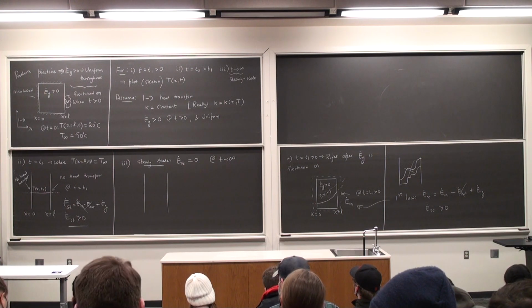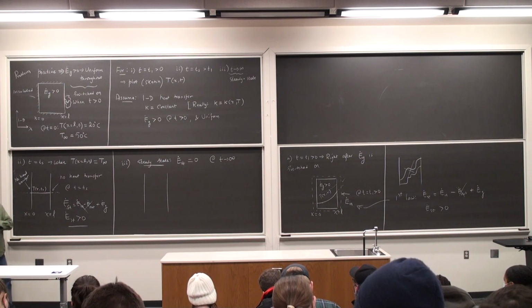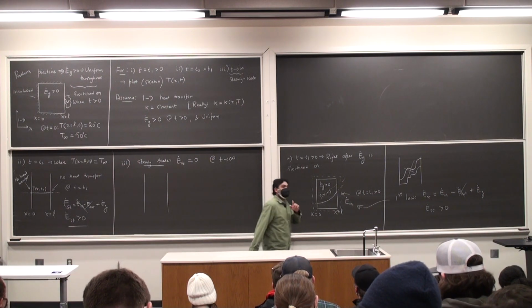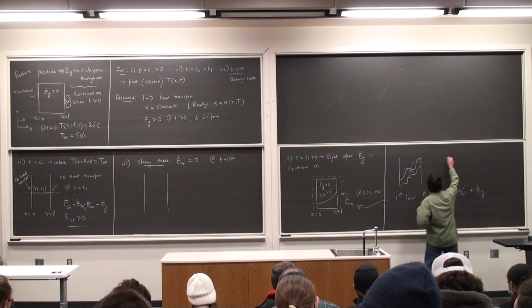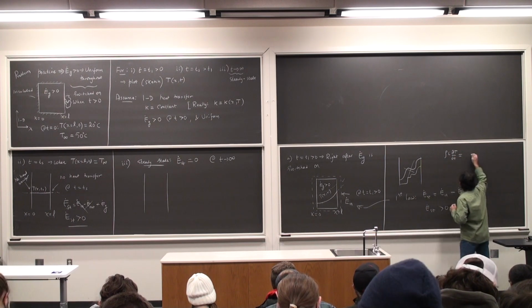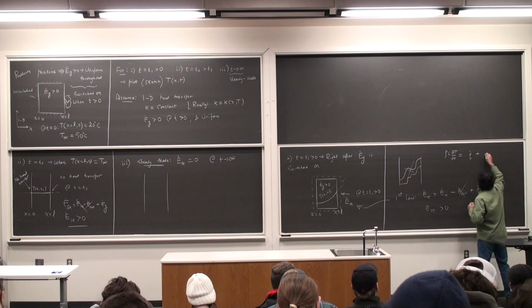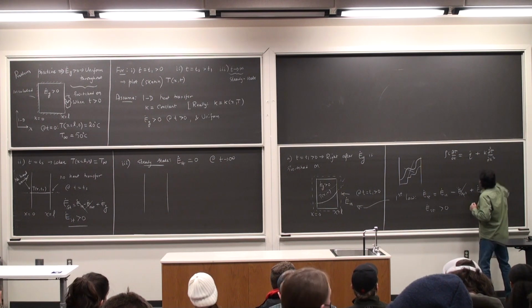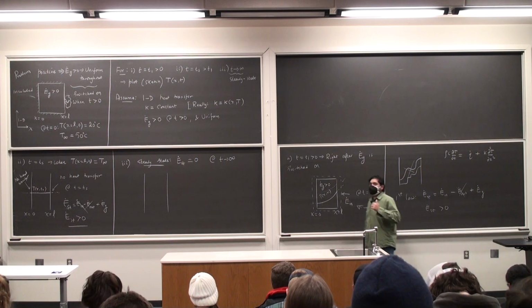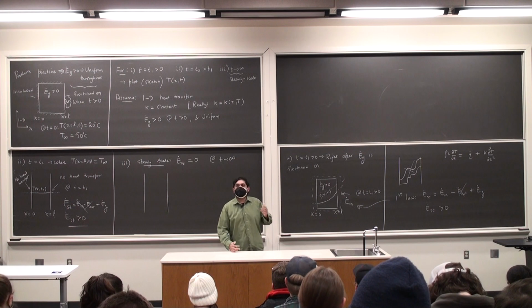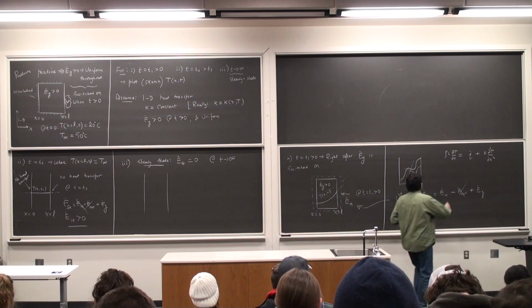And what you'll figure out, we will not be doing this in this course, it falls beyond the scope of this course. You can solve the one-dimensional heat diffusion equation. Okay, so you can solve this equation, which is some q dot plus k times d square T by dx square. One can solve this equation. A common solution for this equation is called the Ogata-Banks solution.